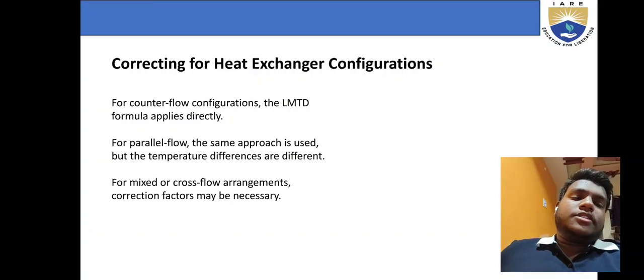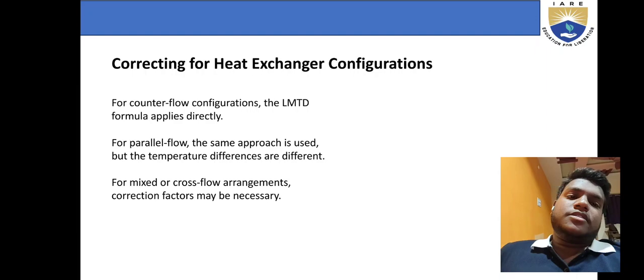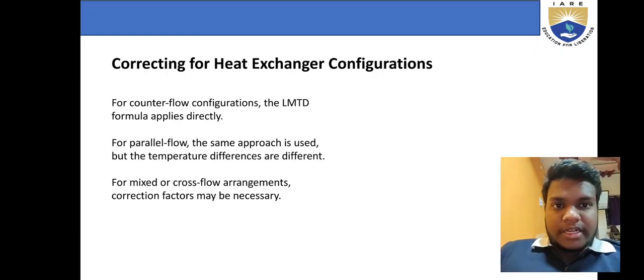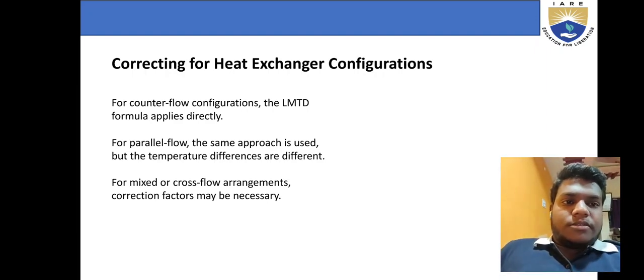Correcting for heat exchanger configuration. For counterflow configurations, the LMTD formula applies directly. For parallel flow, the same approach is used, but the temperature differences are different. For mixed or cross flow arrangements, correction factors may be necessary.